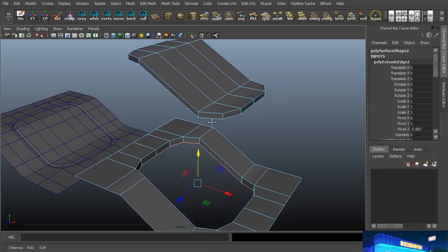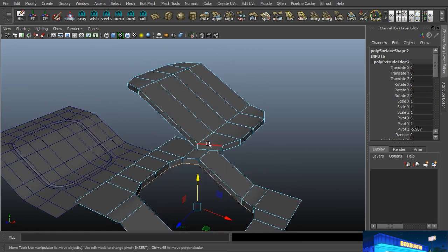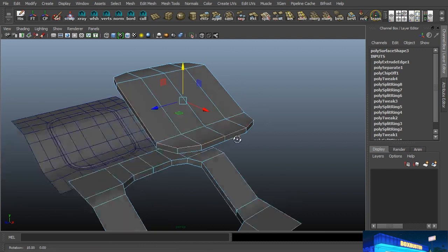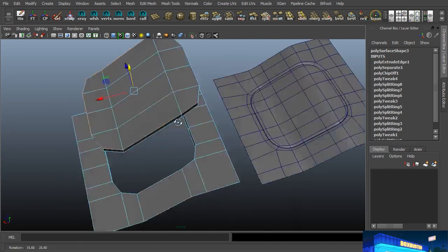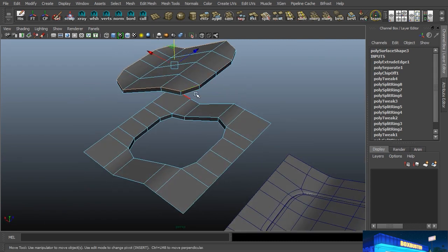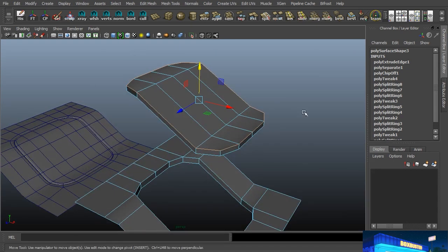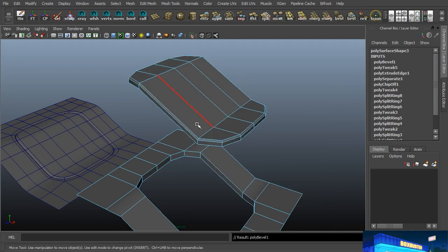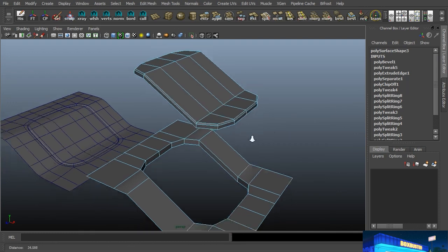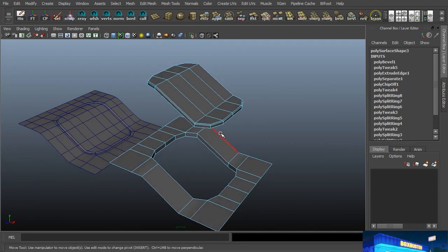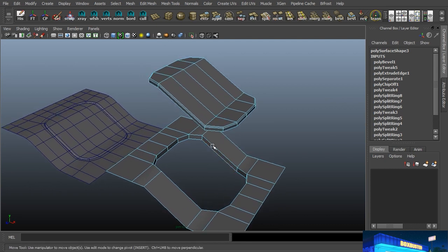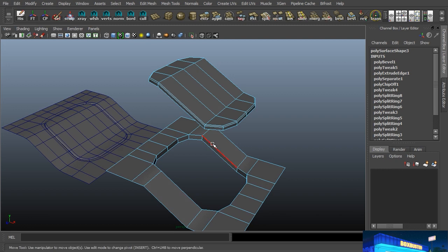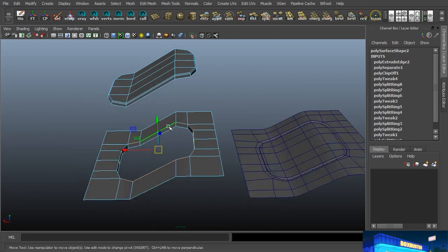And now we need a little bit of beveling on these edges so that we can keep all of these shapes when it smooths. All right, so I'll grab all those top ones and we'll go to Edit Mesh and we'll bevel that. Now, this poses a little bit of a challenge for us because we want the bevel to be the same size on both of these. Let's do this one really quick while we're at it, and then we'll worry about that.